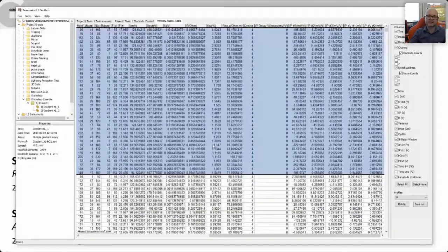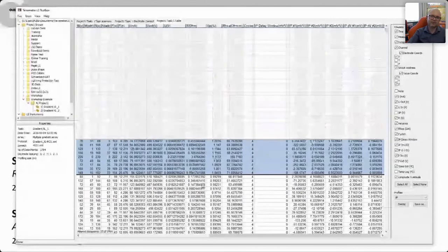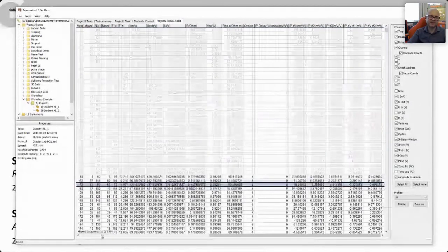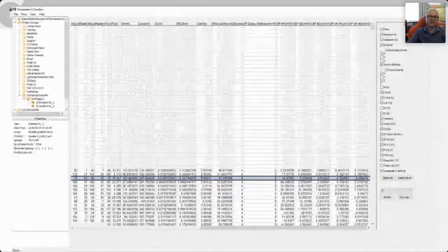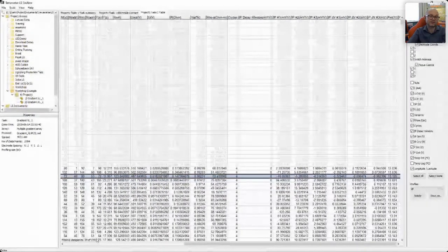If it was a noisy site, then you might set your threshold a little bit higher so that you can maintain a few more data points. But here, I'm going to cut it out at 1%. So I just right click and say filter, and they're all gone. I can see down at the bottom that I've taken out 37 of 2,794 data points. That's not too bad.